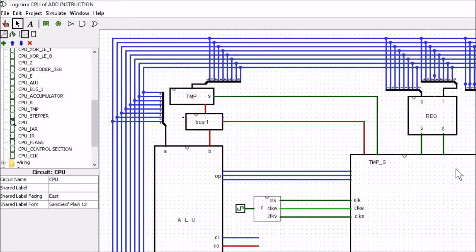So one thing to notice is that in Logisim you can't have a single pin for an input and an output. They have to be separated into an output pin and an input pin. So that's what these pins are for. And you can see we've got the splitter here that splits it up into the 8 individual bits that go to the bus. So everything gets connected on to the bus. You can see this all the way around. So let's have a little look in the 3 extra sections.